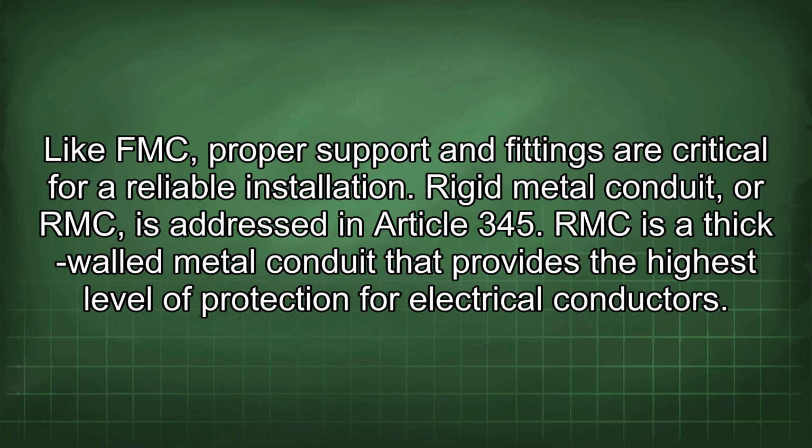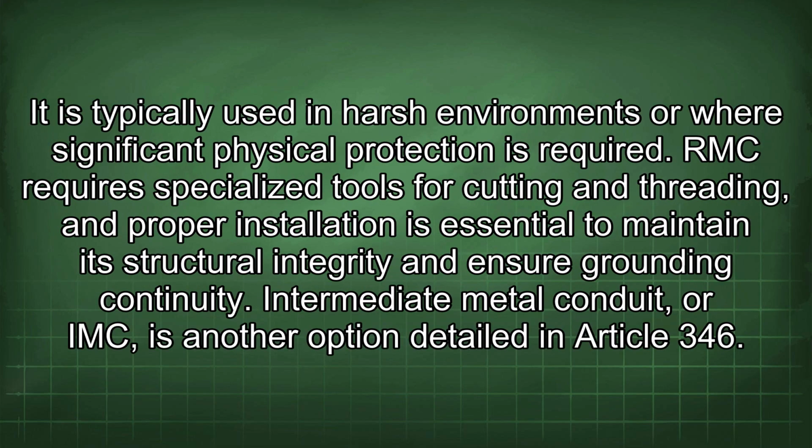Rigid metal conduit, or RMC, is addressed in Article 345. RMC is a thick-walled metal conduit that provides the highest level of protection for electrical conductors. It is typically used in harsh environments or where significant physical protection is required. RMC requires specialized tools for cutting and threading, and proper installation is essential to maintain its structural integrity and ensure grounding continuity.